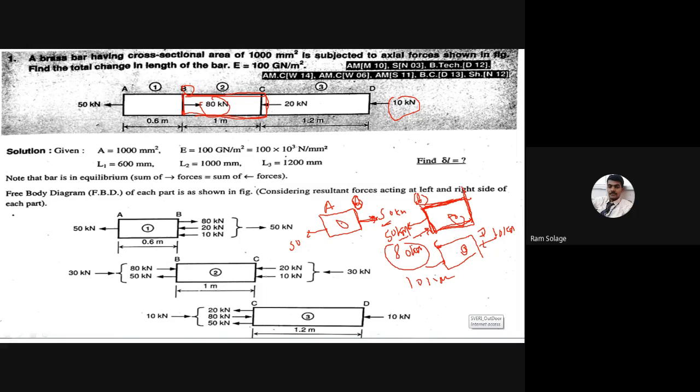Any problem? No sir. I started explaining a slightly technical method to you. If this method seems a little difficult, we will look at another method. Pay a little attention. Now look, one force is 50 kilonewton, a tensile, and another force is 80 kilonewton, a compressive. We have to find the resultant. How to calculate the resultant? One force is tensile, 50 kilonewton, and another force is 80 kilonewton, compressive. I want to calculate the resultant of these two forces. How to algebraically calculate the sum?